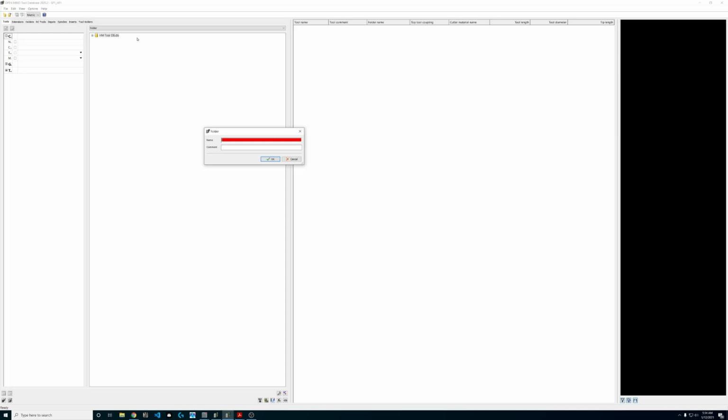If your tools are like most shops and they're spread out everywhere and maybe a little decentralized, then just organizing it by popularity, like, we always buy these tools from Helical or these tools from Fraser or these tools from OSG, so we'll do it by brand name. If you have a centralized tool crib, then maybe they're all organized by type. You have a cabinet that just has 3 flute end mills for aluminum.